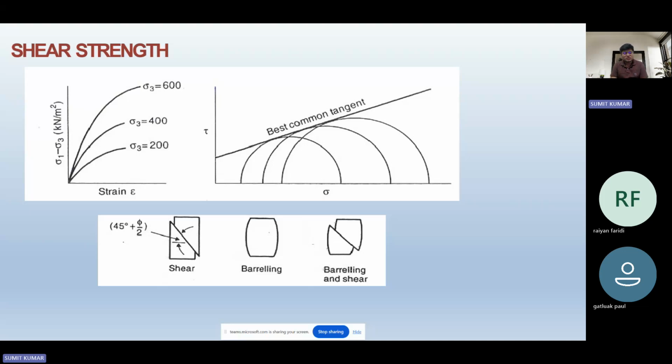But what is different over here from the direct shear test? This question must come in everyone's mind. So the basic difference between the direct shear test and the triaxial test is the drainage control, as we have mentioned very clearly in the very first point of the discussion while elaborating the triaxial test.